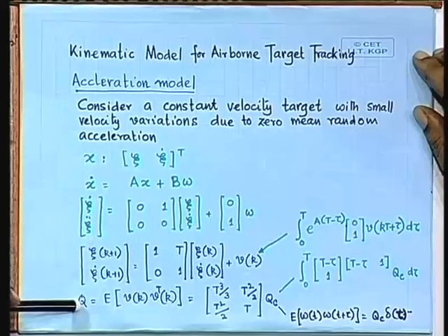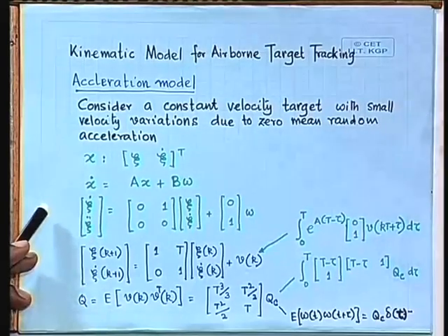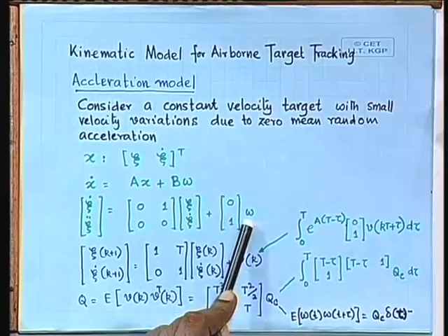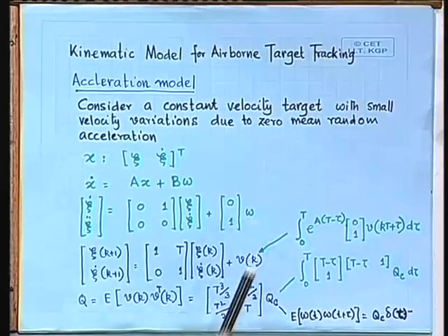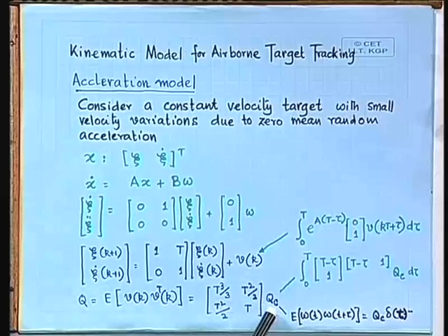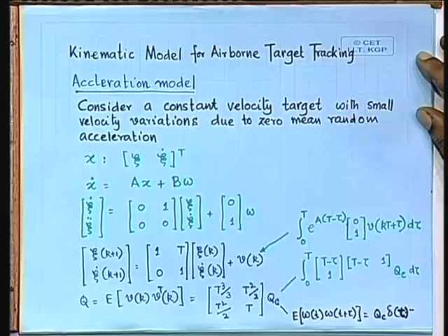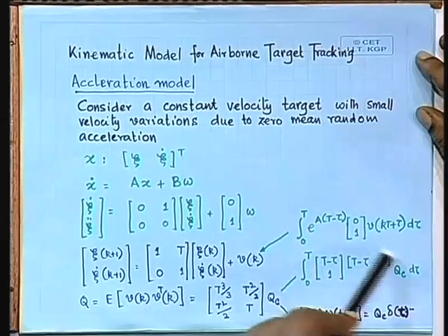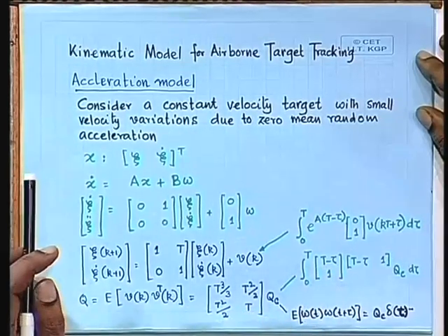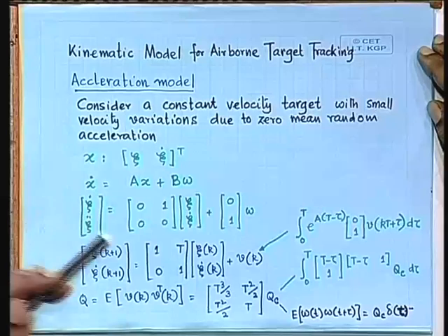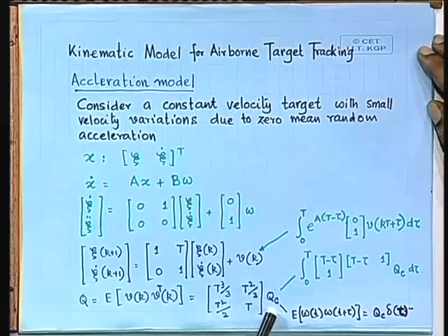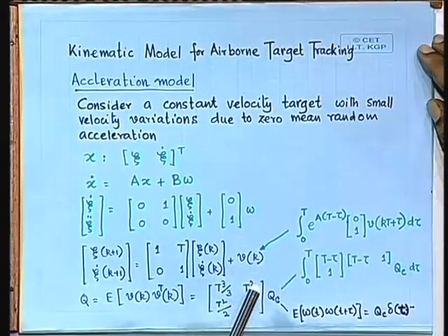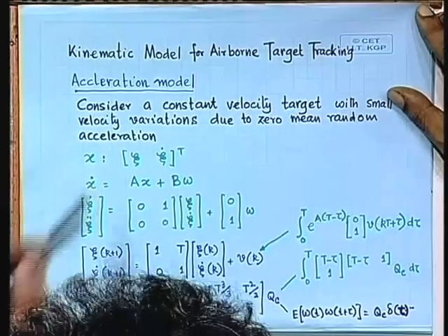Now you have to estimate what is q, you have to now get the discrete time estimate of q, that is the process noise. So if you have a continuous time process noise, the discrete time process noise is actually related to the continuous time process noise by this matrix. We have already found this, so this will turn out to be this, that is simple. So if you know the continuous time signal covariance, this will be the discrete time signal covariance, so that they will be related by various functions of the sampling time, right. So this is my model, okay.